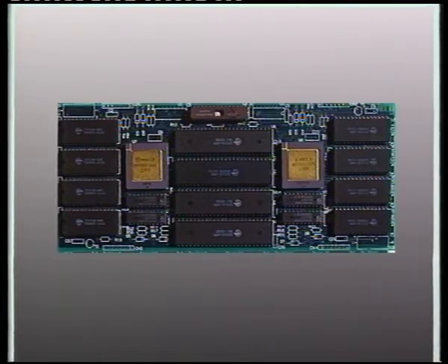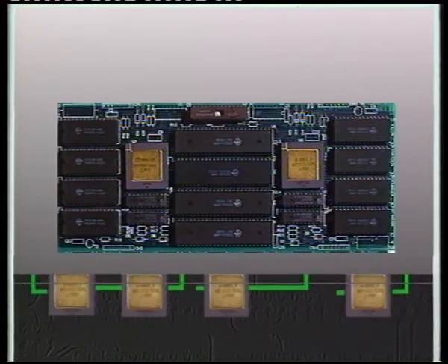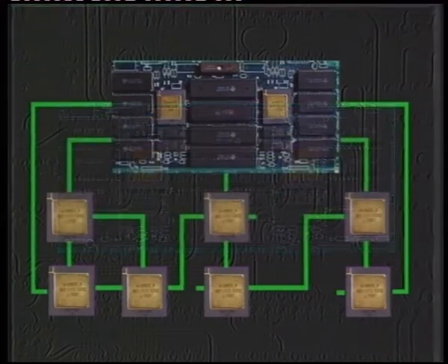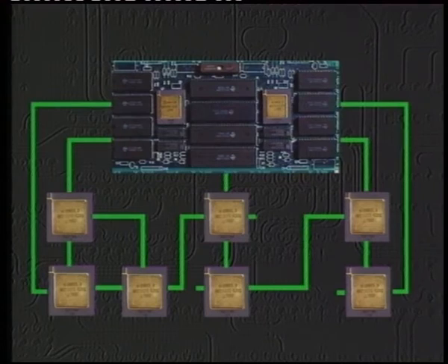Processes running on each of the two transputers can therefore exchange messages with 32-bit parallelism. The remaining components on the board provide the NMOS standard interface to the motherboards. Another important feature of the project is the complete transparency of the architecture with respect to tools available for implementing and debugging transputer-based network software.